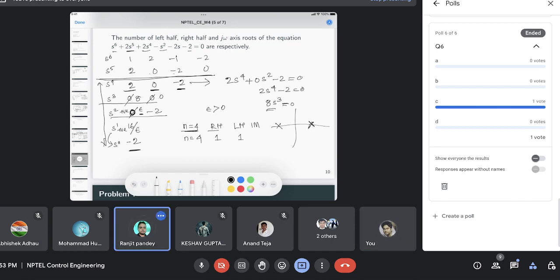Yeah, so 2 poles will be in the imaginary axis, right? And how many poles have you encountered till now? This is 4, right? This is a 6th order system. You have accounted 4 poles already. So before this auxiliary polynomial, is there any sign change? One sign change, sir. Yeah, one sign change only for this auxiliary polynomial, that we already accounted here, right?